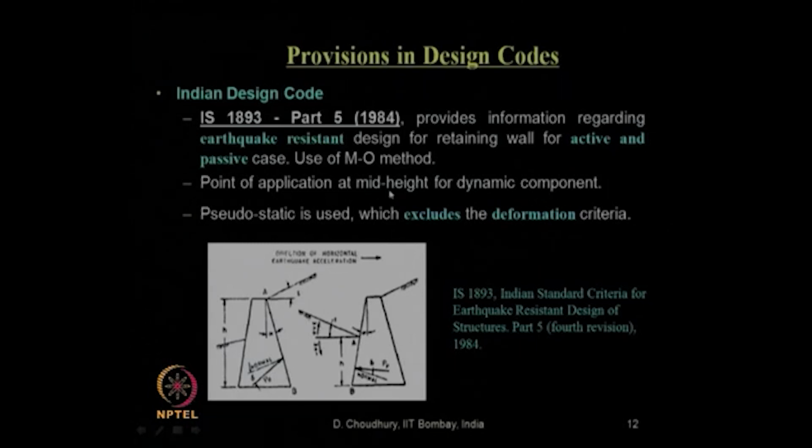Also, the point of application is a thumb rule. It says that it acts at the mid height only for the dynamic component. The static component acts at 1/3 from the base, but the extra dynamic component acts at the mid height.